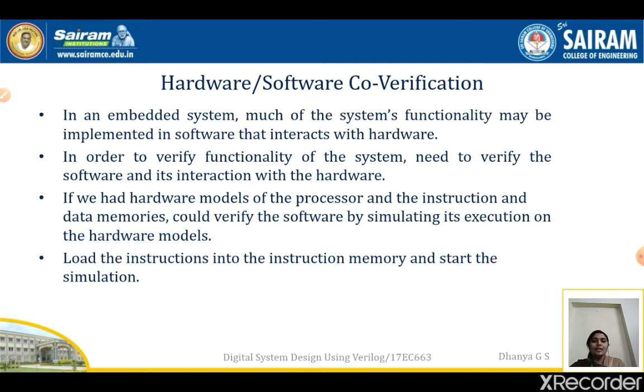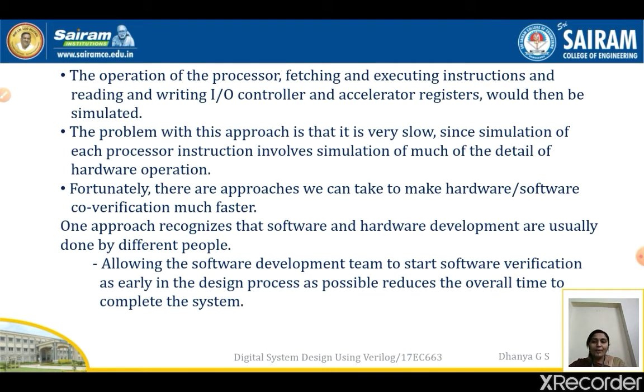Load the instructions into the instruction memory and start the simulation. The operation of the processor, fetching and executing instructions, and reading and writing I/O controller and accelerator registers would then be simulated. That means each and every component which you have in the hardware has to be simulated using software. The problem with this approach is that it is very slow, since simulation of each processor instruction involves simulation of much of the detail of hardware operation. So this will make the system get verified or simulated very slowly.